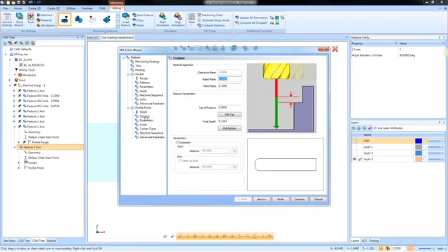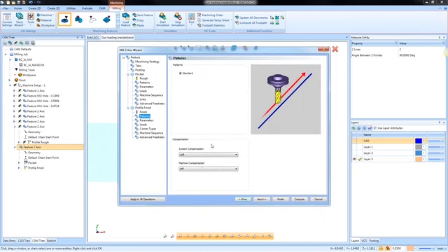And then with that profile, that's where I could use system comp and machine comp. System comp is when BobCAD offsets for half the cutter. Machine comp is where you can throw a G41 or G42 in there so you can dial in the wall. Okay, so the pocket cycle doesn't have any comp settings. The profile setting does have a comp setting, so you can use G41, G42.